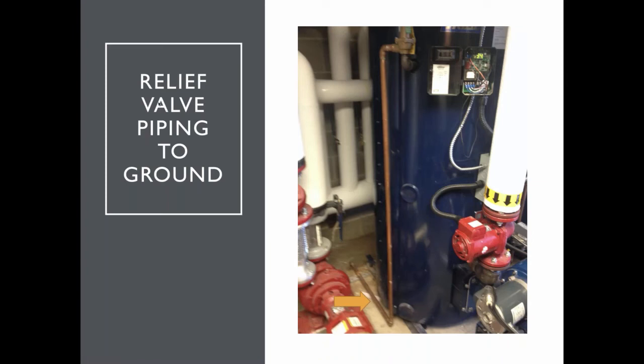We were called to consult on a job, and this was an interesting job where the expansion tank was flooded, and the relief valve kept weeping, open and closed, open and closed. Well, the copper tubing is piped all the way down to the ground. And what happened was when the relief valve kept opening and closing, this copper kept expanding and contracting, expanding and contracting. Right here on the relief valve, this was a fulcrum. It finally just snapped, and all the water in the system came out and flooded that boiler room. So you want to have a little bit of space for the expansion and contraction if that ever happens.